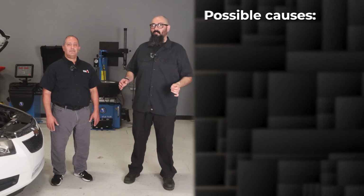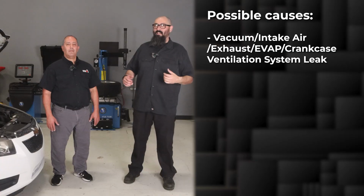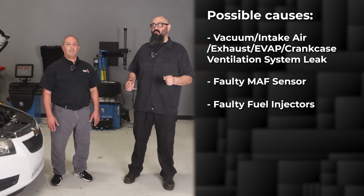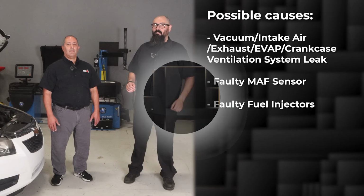For P0171, there are several possible causes, including vacuum, intake air, exhaust, evap, or crankcase ventilation system leak, faulty MAP sensor, that sort of thing. If any other trouble codes are stored, make sure you diagnose and repair those first. Do not continue troubleshooting this code until all related faults have been corrected and taken care of.